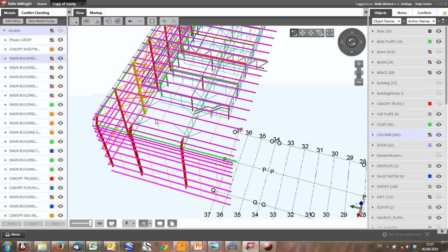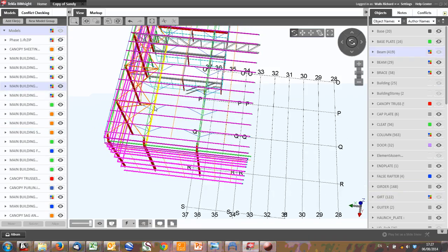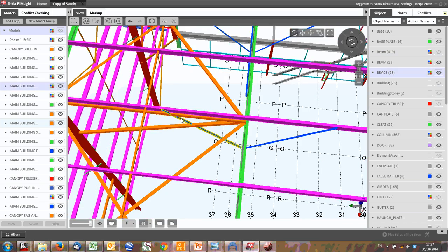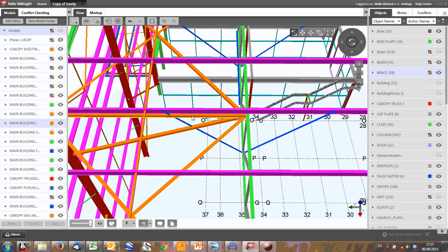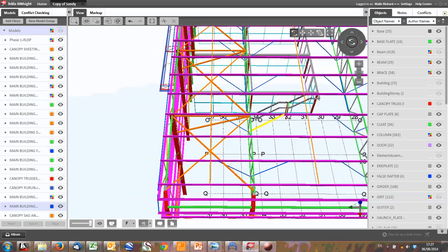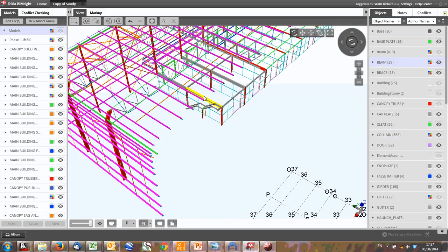For instance, let's say you couldn't put braces here for some reason. If there were penetrations to the roof or ducts or something weird, and you couldn't put a brace bay here, you put it in the next bay, then you just take your pipes all the way through. So you go through that bay. So there's your pipe in orange there, I've highlighted. You just put one there and one there. You can take your load down there and then take it out the door. So those are ways you can actually move forces through until you can get them to a place where you can handle it.